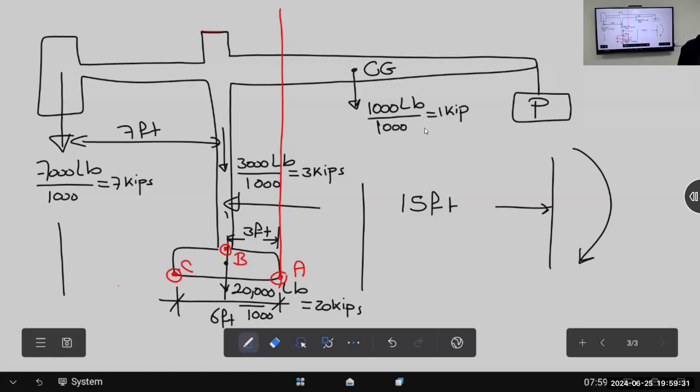But when we say equilibrium, it means stable. The moment should equal 0. Now one equation, as I told you: B multiplied by distance. B multiplied by 15 minus 3 equals 12. Correct or not? The boom has weight and will give you a moment as well. This distance is 5 foot, right? 5 minus 3 is 2, multiplied by 1 kip. Coming from the right hand is this moment.